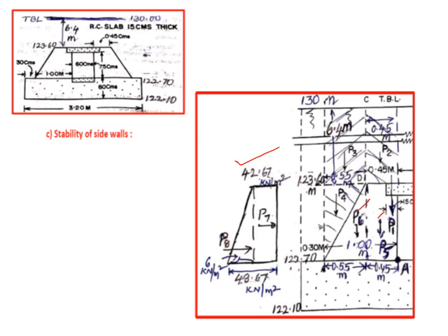Similarly 6.4 plus 0.9 at the bottom, which will come to 7.3, that is 1/3 into 20 into 7.3 gives 48.67. You can divide into suitable portions, that is rectangular portion is P7 and triangular portion is P8. So what is the remaining ordinate for this? 48.67 minus 42.67 comes to 6 kilonewton per meter square. So therefore in order to calculate P7, it is the area of this diagram, which is 42.67 into 0.9 into 1 is P7. Half into 6 into 0.9 into 1 gives P8.